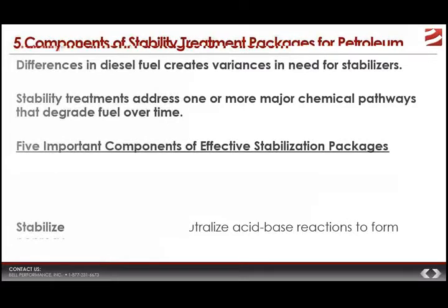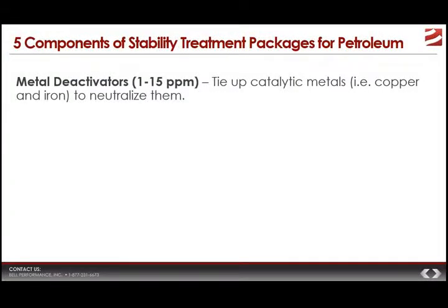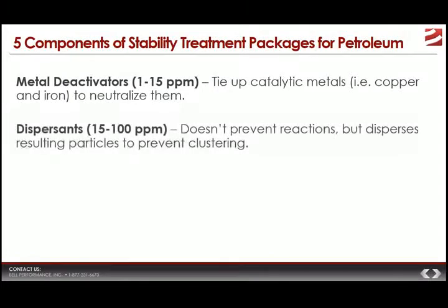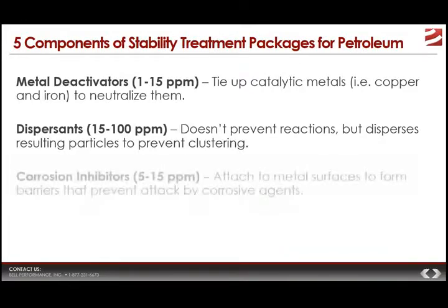Third thing it needs to have is a metal deactivator. Remember we said there are catalytic metals that speed up reactions. A good stability package will have a metal deactivator that neutralizes these. It will also have a dispersant. A dispersant is going to take the heavy molecules that have started to drop out of solution. It's going to keep them away from each other. It's going to keep them from reacting, which means they don't get bigger, which means it stretches out the effective storage time of the fuel.